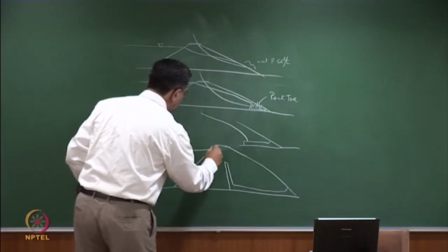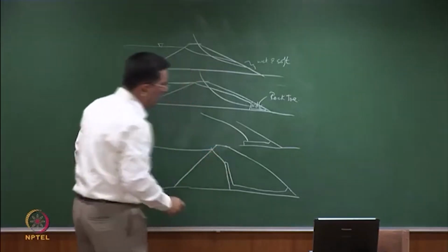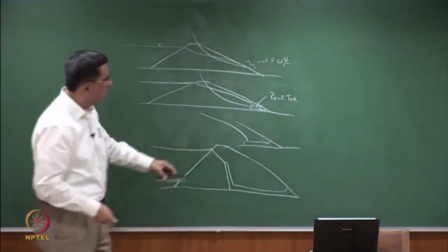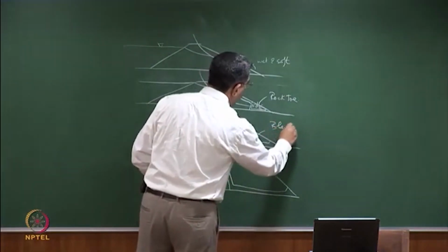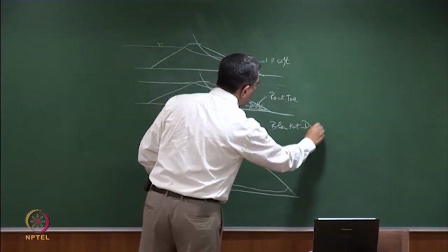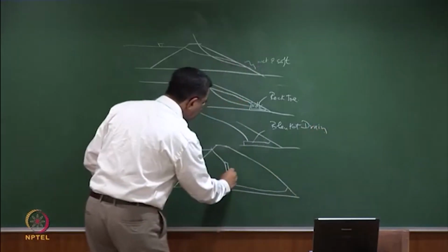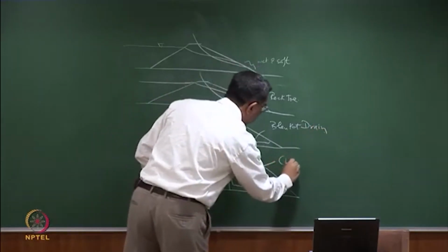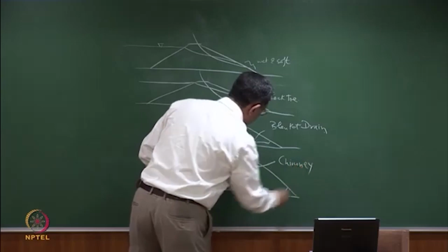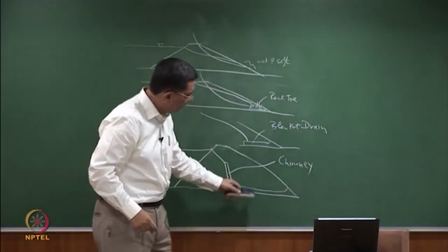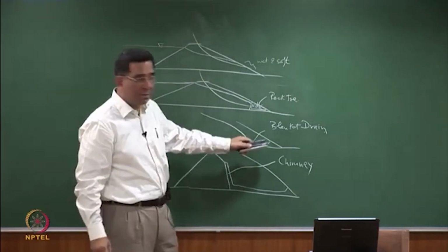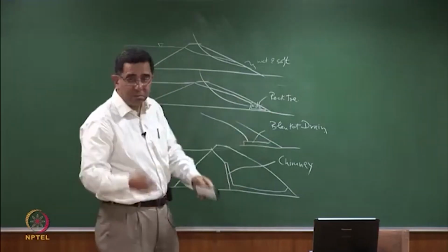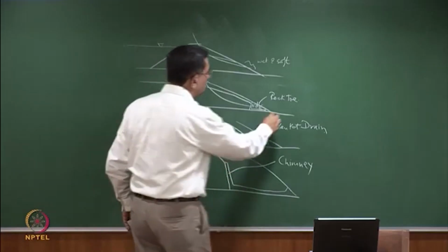Then I am through the chimney drain. So this is what? A blanket drain. And this is a... So in this arrangement, you have a chimney drain, a horizontal blanket, and a rock toe, right? Here you have a horizontal blanket and a rock toe, and all of them have a toe drain at the end. A toe drain is something which is here.